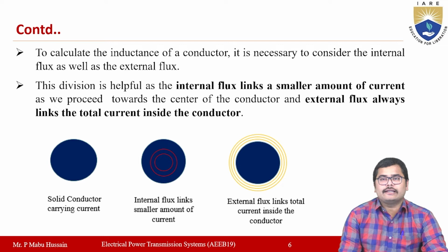To calculate the inductance of a conductor, it is necessary to consider the internal flux as well as the external flux. This division is helpful as the internal flux links a smaller amount of current as we proceed towards the center of the conductor, and external flux always links the total current inside the conductor.